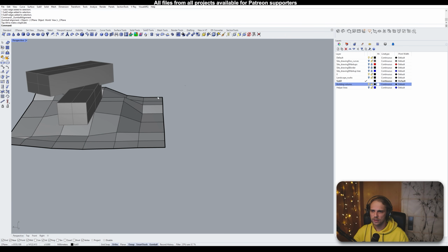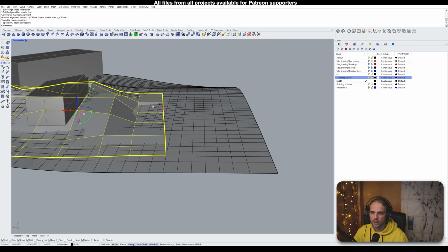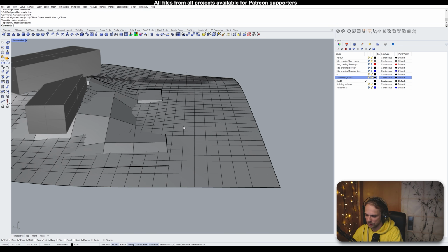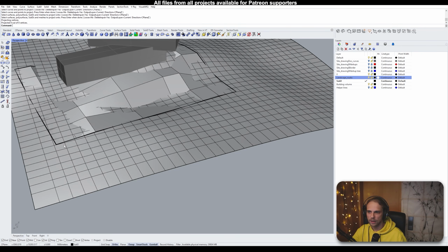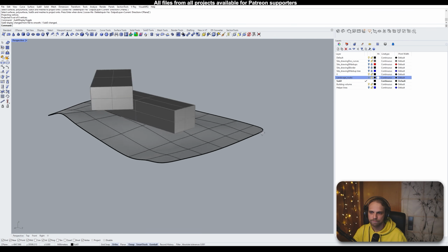At this point, these points right here, I believe we should, let's see, where's my landscape? There it is. The points should be projected back onto this landscape, right? So we project, select only these points this time, enter, onto the landscape, and now they are all following the landscape nicely. Tab. This is good now.